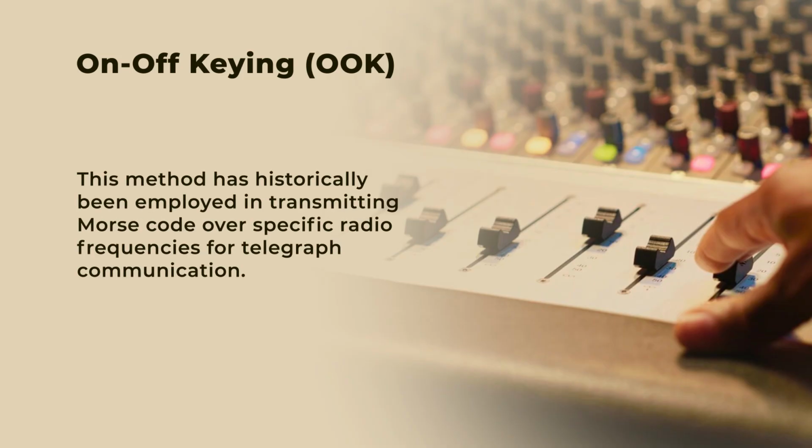This method has historically been employed in specific radio frequency or telegraph communication. However, on-off keying is not particularly efficient regarding spectral usage because the carrier amplitude shifts abruptly with each change in data bit. Therefore, while on-off keying is suitable for transmitting data at low to moderate rates, more bandwidth efficient phase modulation techniques are preferred for higher data rates.